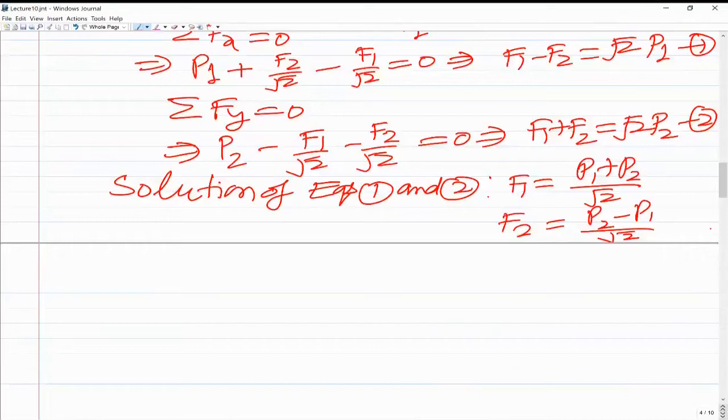So although they may be connected through welding or through a gusset plate, at the joint a plate is there in which all the members are welded. That is known as the gusset plate. But the members would be concurrent, and if it is so, we treat that as a truss structure. In 3D truss structures, the joints are going to be ball and socket joints.